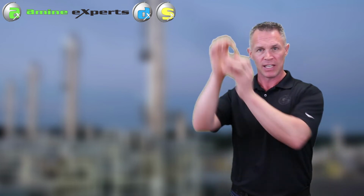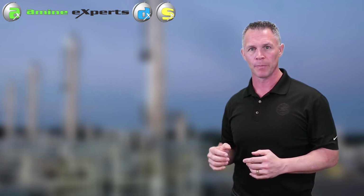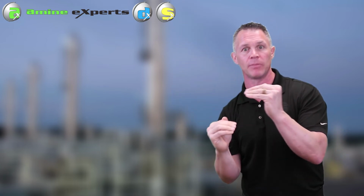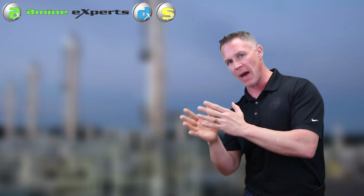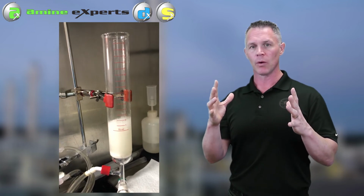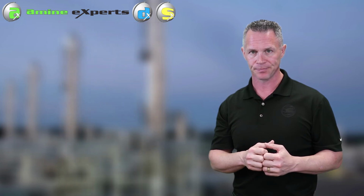In most gas plants, H2S spec is the most important thing that the operator follows. So there are definitely clients of ours where we have them running the amine at the same temperature as the feed gas, or sometimes even colder. It puts them at risk of foaming without a doubt, and so we manage that with proper anti-foam addition. We make sure the anti-foam is effective, we make sure we know the dosage rates, all that good stuff. And just during those couple hours in the hottest part of the afternoon, we inject anti-foam to keep things under control while not going off spec on H2S.